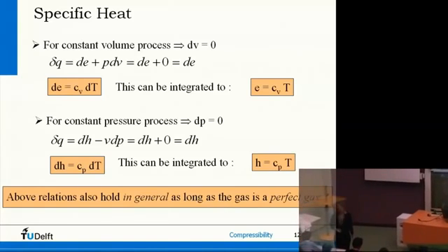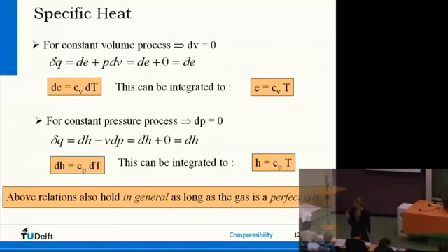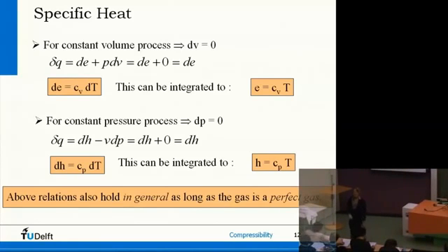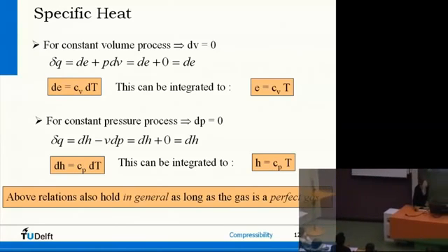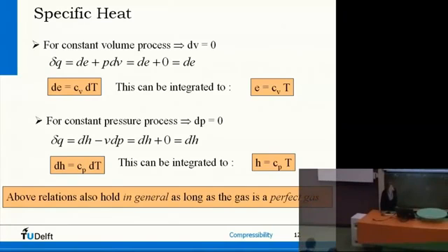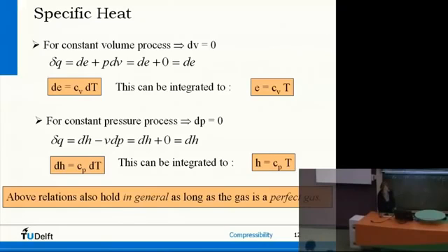So I have a direct relation between internal energy per unit mass and temperature, and it's linearly related, and the only thing that's in there is the specific heat at constant volume, so CV. Now I play the same game, but with a different relation from the first law, where I didn't have dVs, but I had dPs. And of course I play the game now for constant pressure processes, so my dP is 0. I start with a different form, relating the enthalpy to the heat added or subtracted, and that was this form, right? dQ is dH minus VdP. Constant pressure, so dP is 0, so direct relation, changes in enthalpy per unit mass is equal to changes in heat.